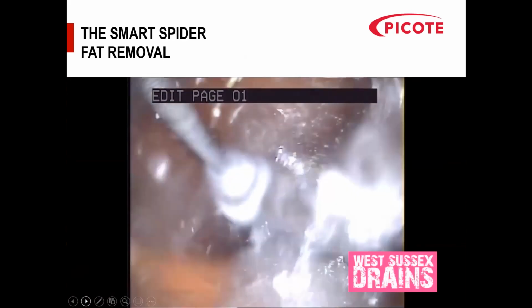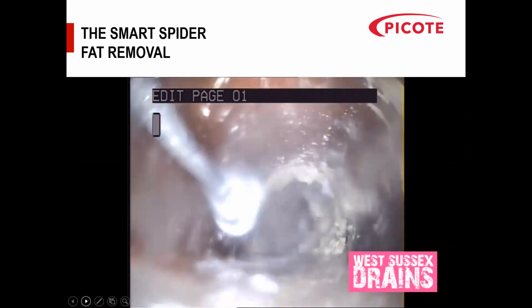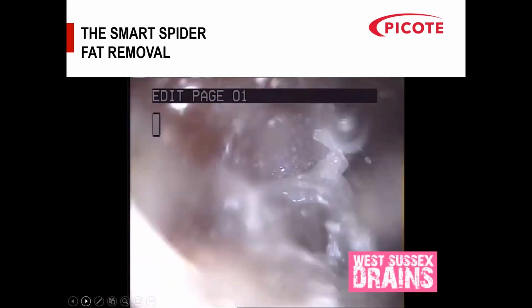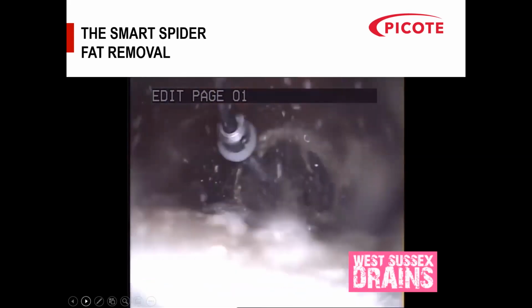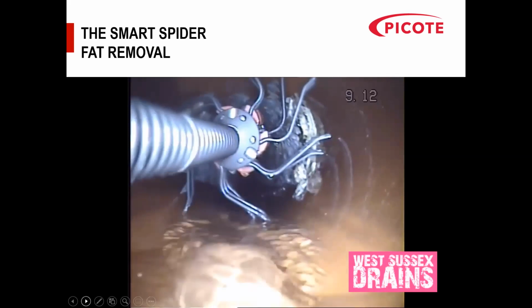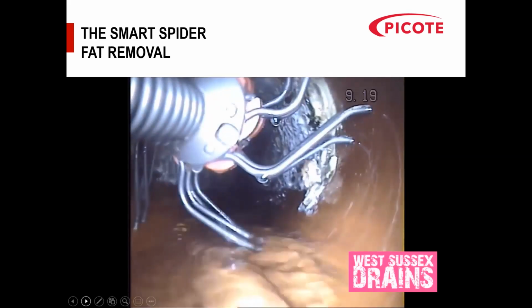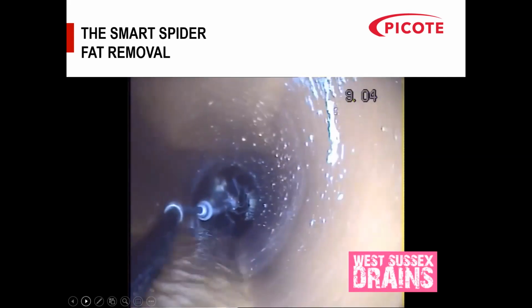Those little legs index in and out, and what they do is they chip away at the fat, break it into very small particles, which you can then flush out of the pipe. So this is the first pass through, and it started doing it. Now they've just stopped it and put the camera down. So it's taken probably 90% off on the first pass.